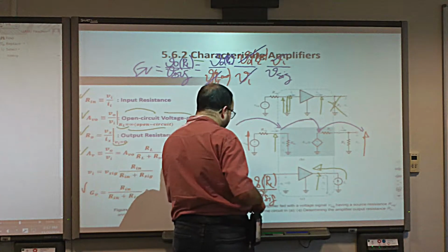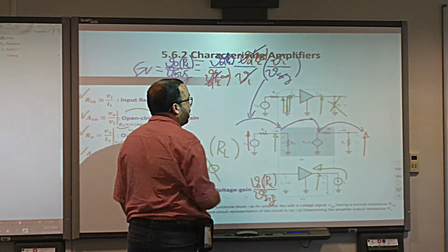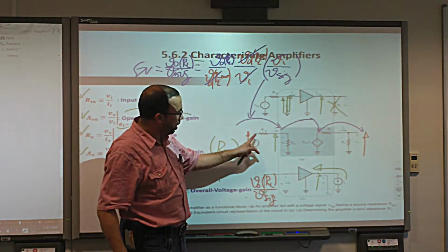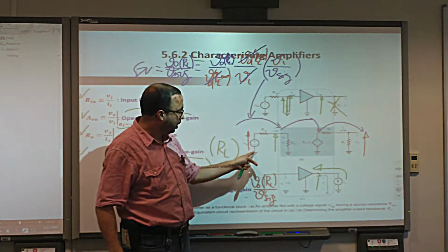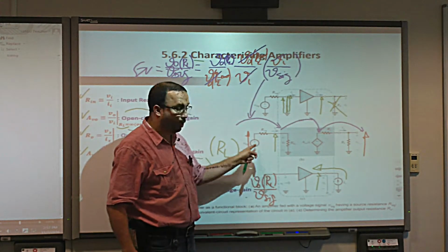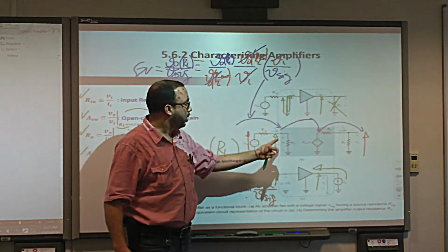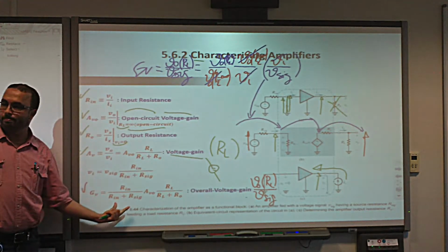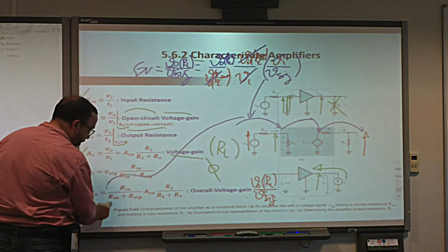Alright, so this is basically the transfer of voltage. See that the input here divided by the total voltage here is a voltage divider, yes or no? This voltage from this point to this point, but this one is only from here to here. This is a voltage divider. So I know this relation in this case. It will be Rin divided by Rsig plus Rin, yes or no?